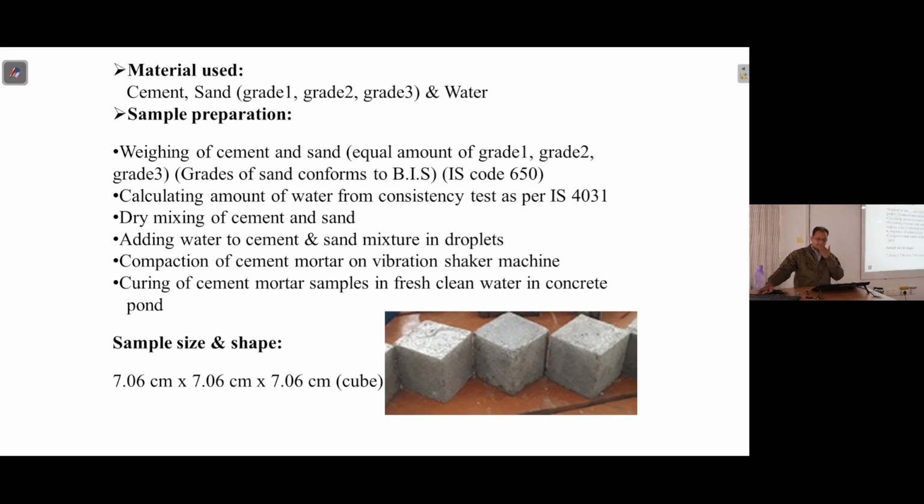Then next, we wanted to try the most commonly used form of cement. So these experiments are with mortar, because generally pure cement is not much used; either you use mortar or concrete. We could not do much with concrete so far, but we tried it with mortar. So these are the standard cubes of mortar, and this is the usual procedure prescribed for their fabrication.